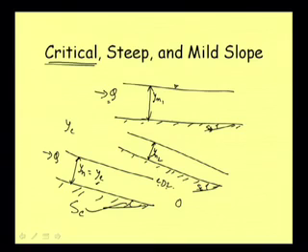So, that is the concept of critical slope, and then to find it mathematically, if we use Manning's equation, then we can write Q is equal to 1 by n, then R to the power 2 by 3, then S to the power half. Now, when the flow is in critical condition, our hydraulic radius we can write as R C, that is, the hydraulic radius corresponding to the critical depth, and then this slope we will write as S C.